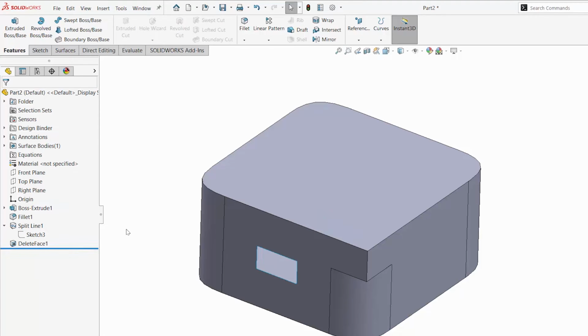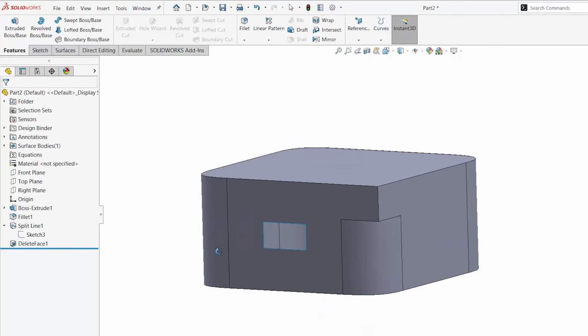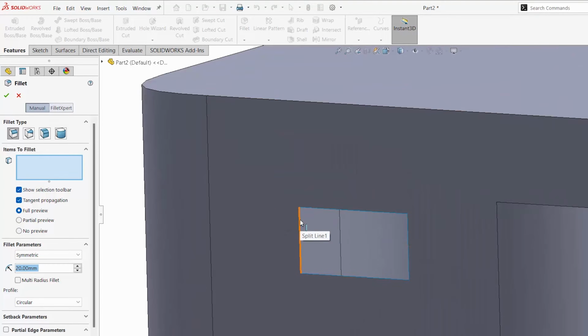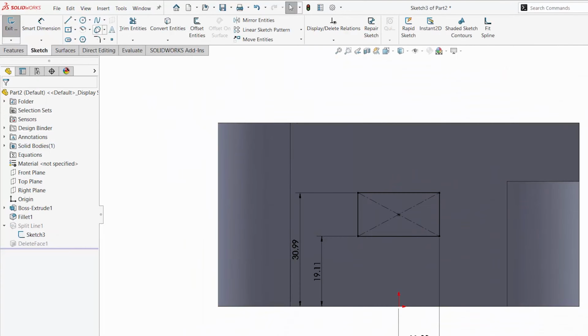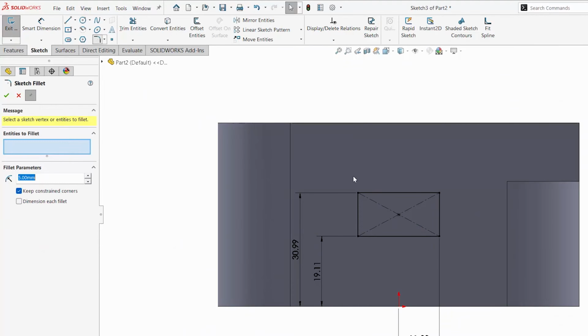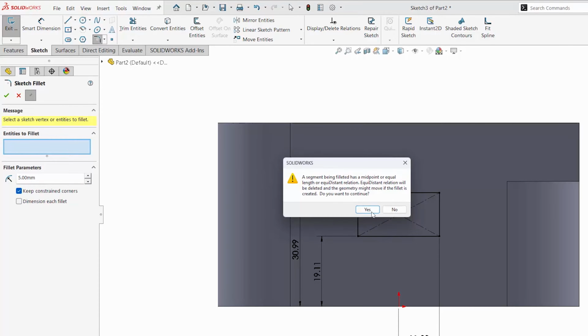Now, where you may want to use a sketch fillet would be if we needed to do a complex loft or surfacing solid operation between this body and another. Simply using a sketch to create that split may not have the right number of entities to make our loft look smooth. So we would want to use a sketch fillet feature to actually get this profile.